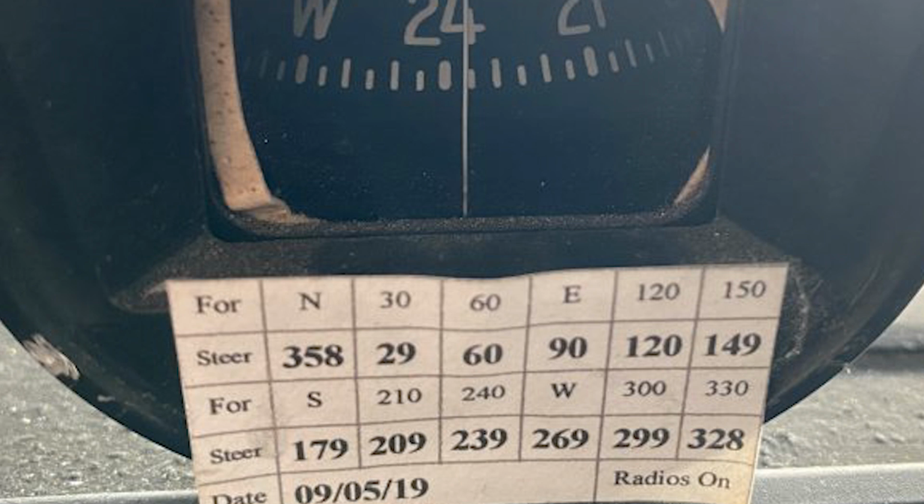and then ultimately it will come down to the compass card, which basically says that, hey, look, with the radios on and with these different configurations, the compass, whenever it's pointed at 180, will actually read 175. So you always want to take deviation into account when you're doing navigation. You want to plot it all out and say, oh, look, I need to add 5 degrees because my compass card is off. But that's deviation. That's something that you as a mechanic will have to become intimately familiar with, because compass swings, the process for calculating that deviation, is something that you'll do on a regular basis.